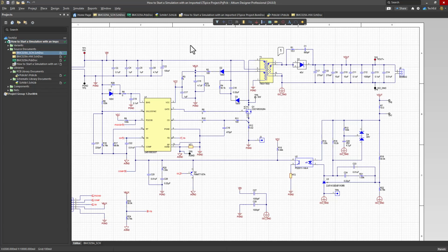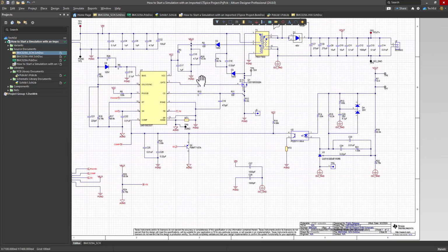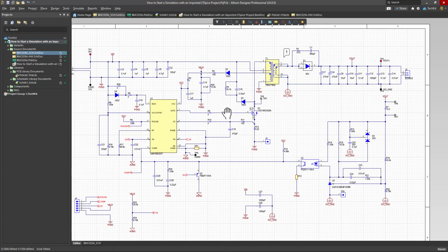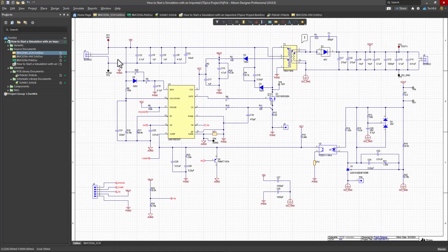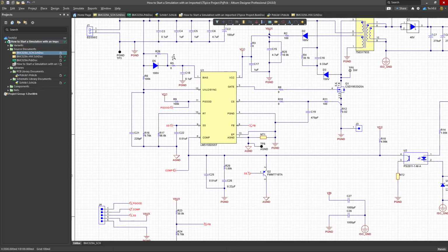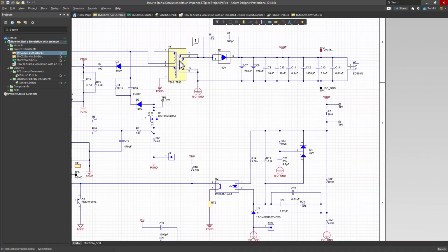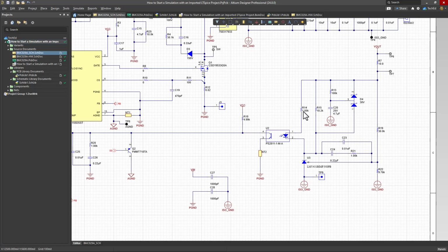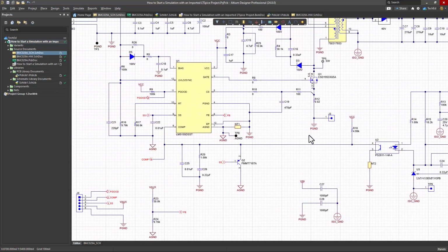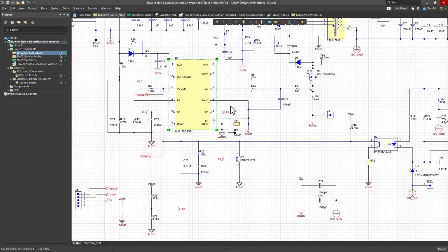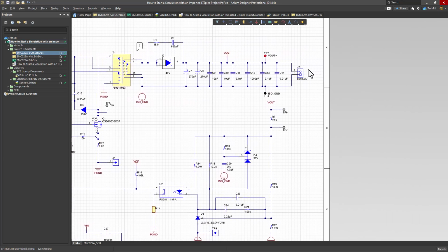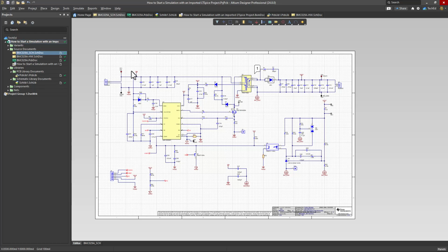So whether it's the Apple power supply, for your MagSafe, whatever, whether it's your Windows PC power supply, it's going to have some kind of flyback in it, because the flyback can take that AC, 120 volts AC, and take it through a step-down transformer, put it through some capacitors to give you a nice clean output voltage. Now you'll have a feedback control. Here's an isolated feedback control. It goes here, it goes into your control device, and then does the control in such a way that you get clean voltage output, clean voltage stable output.